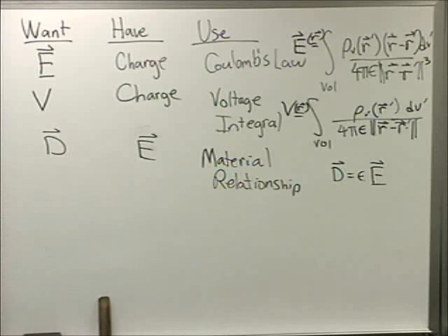We talked about the physical meaning of that. It's the stretchiness of the electrostatic molecules inside of a material. You impress an E field. It makes the electrons go one way. It pushes the positive nucleus the other way. And that makes a countervailing E field that suppresses the total E field for the same given charge flux density through a material. And that makes E look a lot smaller than D proportionately when you start adding stuff.